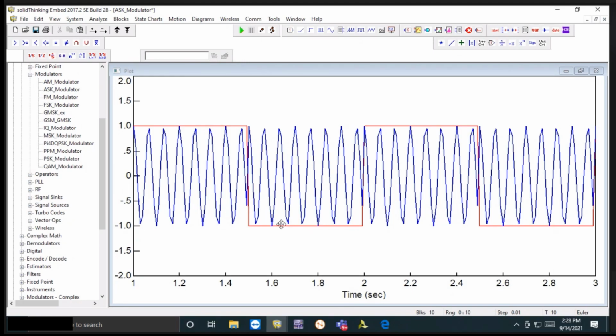So you have seen that basic difference is that in the amplitude shift keying, we were using the unipolar system. It was from 0 to 1, and we multiplied the carrier signal with that, and we have the ASK signal at the output. Now in the PSK, actually, we are multiplying the carrier signal with the bipolar signal going from 1 to -1, and we have a phase shift of 180 degree at the transition point, right? Any query from anybody? Please let me know.